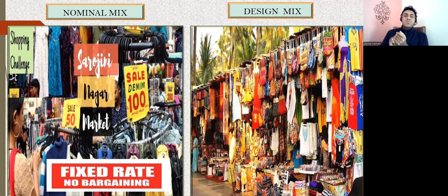In the same way, when we go for the mix design, we do individual testing on the materials like cement, fine aggregate, sand and water. Through my experience and the mix design calculation, finally I'll prepare a very good mix. That comes through experience, and that is what the difference between the nominal mix and the design mix is all about.